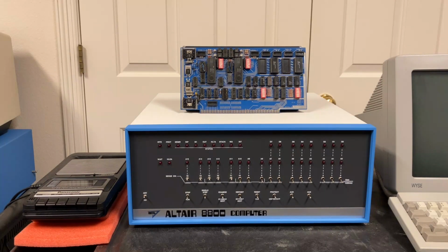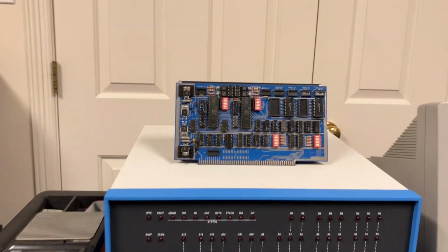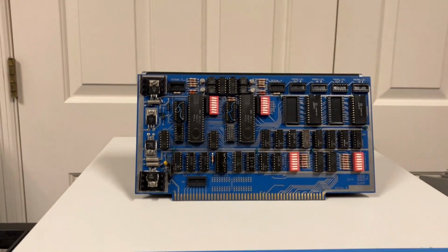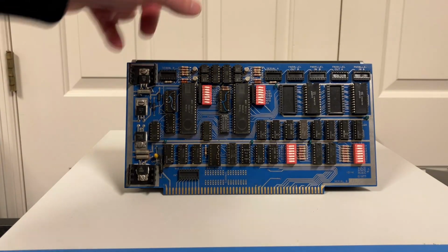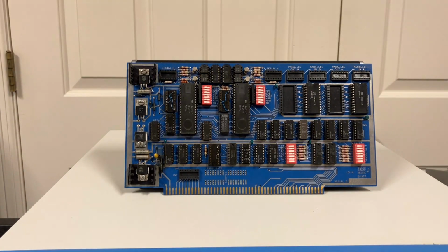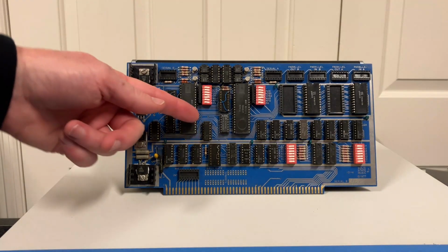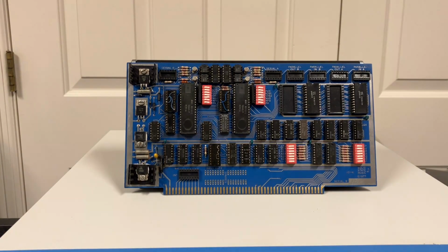Now, the interface that we made in that video was a two-board set, just like the original Altair interface was a two-board set. One of those boards is a fairly standard serial interface board like you see here. This plugs into the bus, and this is what the software actually talks to in order to transfer data. The other board is a modem board. It takes the serial data out of this board and converts it into a pair of tones that then get written to tape, and then of course tones coming off the tape get converted back into serial data that can come into a UART and then be read by the software.